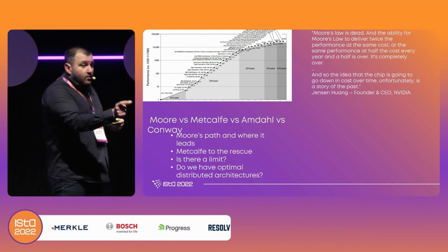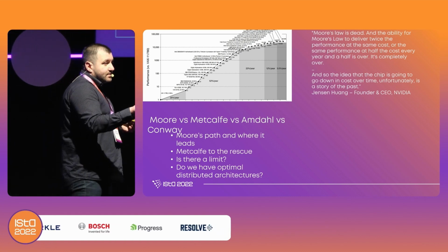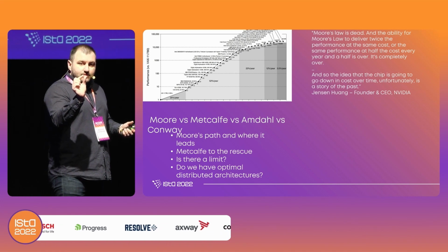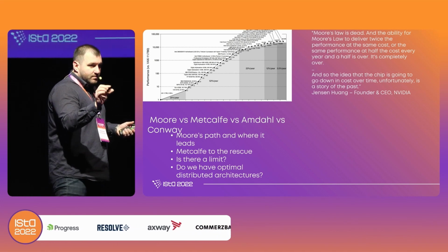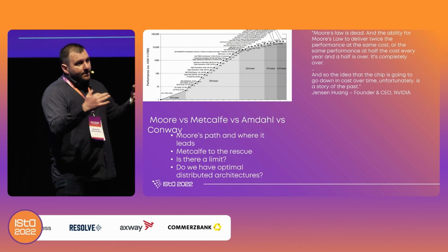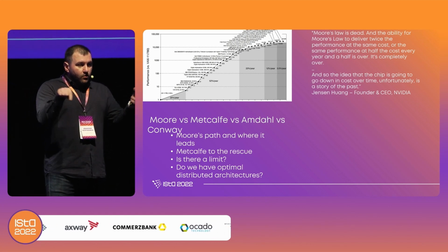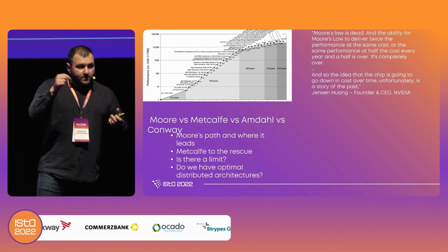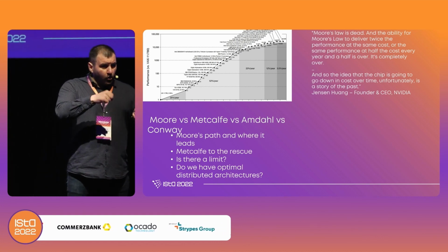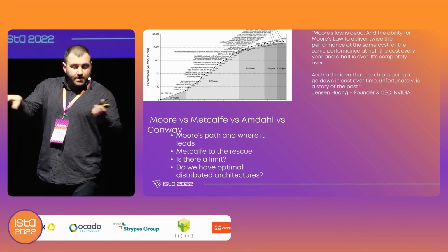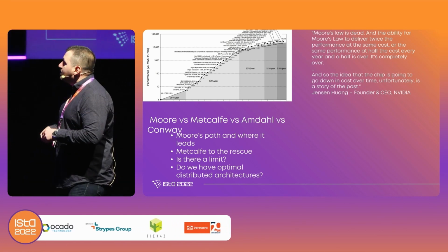And there is an actual physical limit: if the gate length becomes twice as small as now, about 7 nanometers, then quantum tunneling becomes a thing. We can no longer be sure that we are stopping the flow of electrons past the gate, because they can tunnel on their own due to the Heisenberg uncertainty principle.